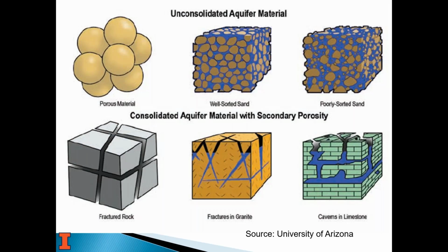And so it really depends on your situation. You may have sand and gravel near the surface where you live. It may be rock at the surface where you live. It could be sandstone, it could be dolomite, it could be granite, and all of that matters. I know there are areas where most of the wells are considered, quote, low flow, like the half a gallon a minute. They only pump at most 2 or 3 gallons a minute, even though they may be 400 or 500 feet deep. And so depth is relative when we talk about wells, because it really depends on the geologic material you're going through and how much water is available through those units.